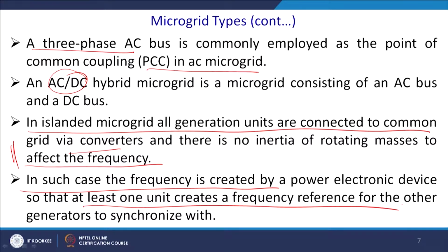Please mind it, in the case of normal synchronization, your biggest generator generally sets the frequency, but here it is not so. Any solar unit, any unit can be the one setting the frequency. We have discussed these entities in detail in our previous lectures. Generally, the energy resource which has the maximum power handling capability is made to control the frequency, like battery, and solar maybe at the point it is controlling.